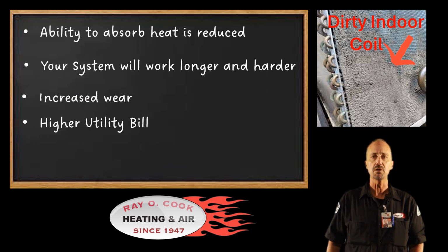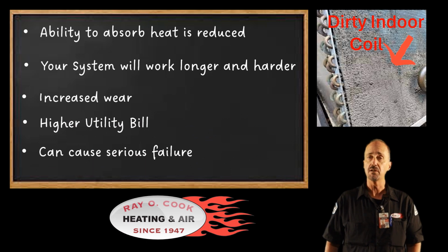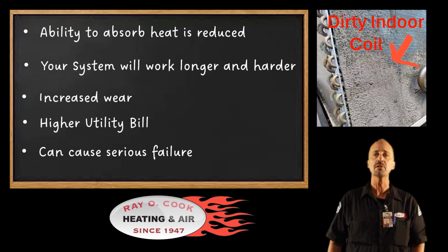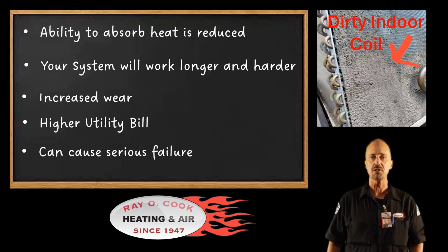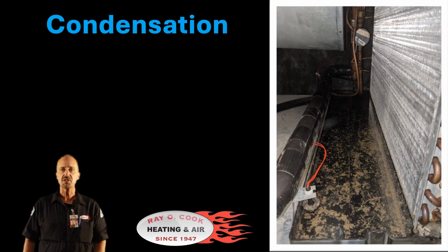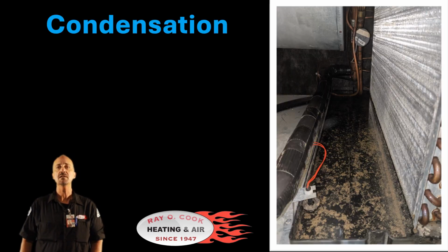If the indoor coil gets too dirty, it can actually cause serious failure of your cooling system. The cleaner your indoor coil is, the more heat you can absorb from your air conditioning unit, meaning your air conditioner is more efficient. What's more, any humidity that is removed from your indoor air happens at your indoor coil. This is called condensation or condensate water.